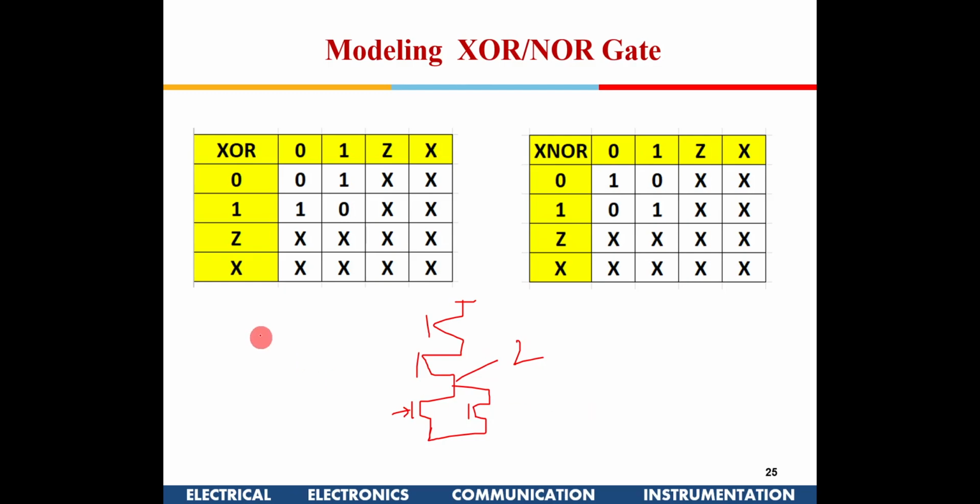Okay. Correct. Now you might want to think that this is open, so can I take all Z inputs as 0, right? That is actually not done, because leaving this open for this particular circuit might appear to be 0, but that may not always be the case.